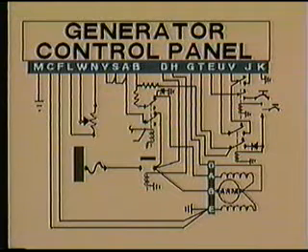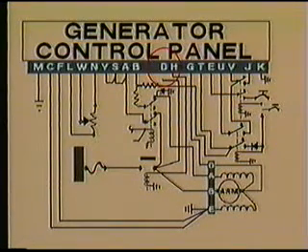Well, first off, let's state that the voltage going back to 0 was correct. The overvoltage circuit in the control panel was sensing this level and properly shut things down. The problem was that the connection at pin D of the control panel was broken. This is the input source for generator voltage to be sensed by the control panel.